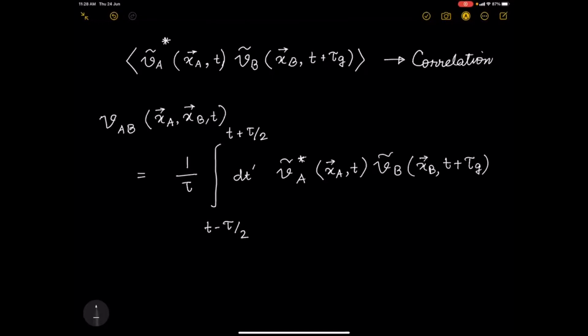If you remember this geometry that Poonam showed you earlier, if the antennas are looking like this from a source there, this is the equal phase plane. So the signal reaches this antenna earlier compared to that antenna. And the time difference between these is what I call tau g. So that's called the delay.